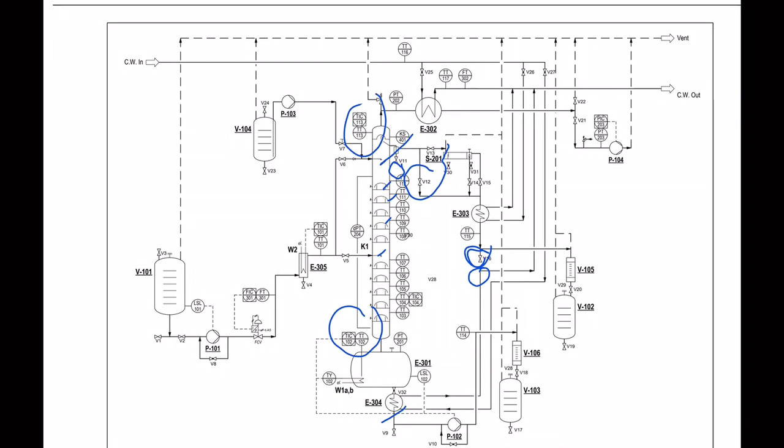Okay, so that is for the top product. Then we proceed to the bottom sample. To collect the bottom sample, we place the beaker below the valve V9. Then slightly open the valve V32 in order to allow the product sample to flow through the bottom cooler. You open slightly for up to 3 seconds. Then you close back valve V32. Then you open the valve V9 to collect the inner sample of the bottom product. Then you close back the valve V9.